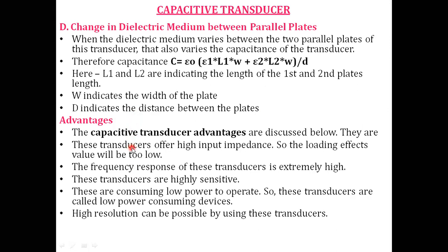Next one is advantages. Capacitor transducer advantages. These transducers offer a high input impedance, so the loading effect value will be very low. The frequency response of these transducers is extremely high. These transducers are highly sensitive and consume low power. They also have high resolution.